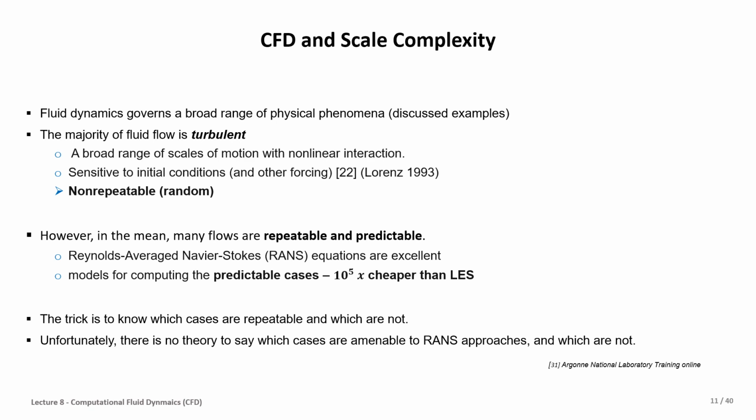Therefore, in CFD, there are 3 approaches to deal with this complexity of scale in turbulent flow. One of them is called Reynolds-averaged Navier-Stokes. This one extracts the average solution for the problem, not the exact solution. For example, if we have a very fine and very tiny scale, maybe we don't get the detail for the problem on that scale. Then the next one is the large eddy simulation, called LES in short.